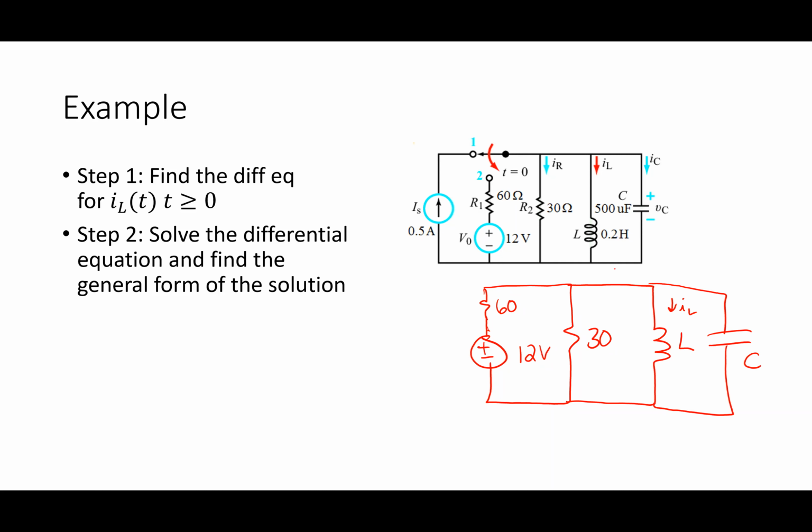This is a situation where I typically want to reduce the circuit. I drew this dash line and said I want to make a Norton equivalent for everything to the left of that dash line. If I'm making a Norton equivalent, what am I replacing that with? A current source, and an equivalent resistance, and where does that resistance go? In parallel, yeah.